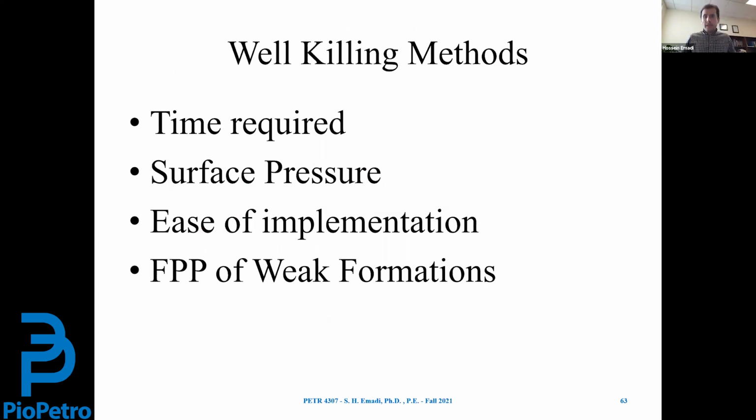However, sometimes we do not have the weighting agent at the location, so we go with the driller's method. Surface pressure. When we are dealing with gas, if you guys remember from the previous lectures, handling gas is way more challenging than handling salt water and oil because of the compressibility of the gas. And remember, we always let the gas expand, because if we don't let the gas expand, what happens? The pressure inside the gas bubble doesn't change, and we see the reservoir pressure at the surface, which is not desirable. So we need to consider what surface pressure we are expecting.